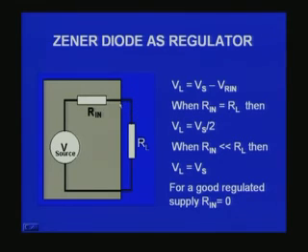So, when I say I want voltage regulation, what I mean is I am attempting to make the internal resistance of the source, by some means, a very small value, or if possible ideally 0. That is what we mean by regulation: trying to reduce the internal resistance, so that the output voltage will always remain constant irrespective of the current that you draw through the load.